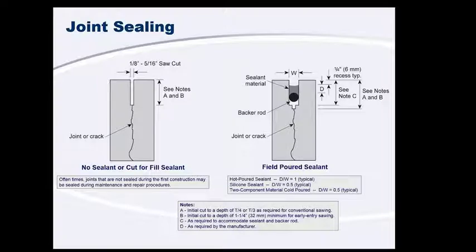What we'll end up doing is putting a backer rod in there. The reason for that backer rod is to make sure that your sealant isn't adhering to more than two surfaces. So we've got the left wall, we've got the right wall. We don't want the sealant to be on the bottom as well. What will end up happening is if we're sealing to 3 surfaces, that crack will actually propagate up straight through our sealant, and so we're trying to avoid that as best we can. Additionally, by having that backer rod in there, you don't need quite as much sealant.